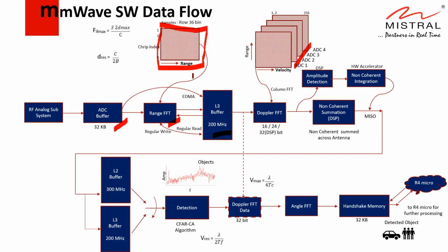The FFT-performed data are used for data processing algorithms like non-coherent integration, and also amplitude detection, the magnitude detection. You can also perform CFAR algorithms. So the different algorithms are computed based on the FFT data, and the processed data is given to the host, a DSP, or a microcontroller for the application processing.